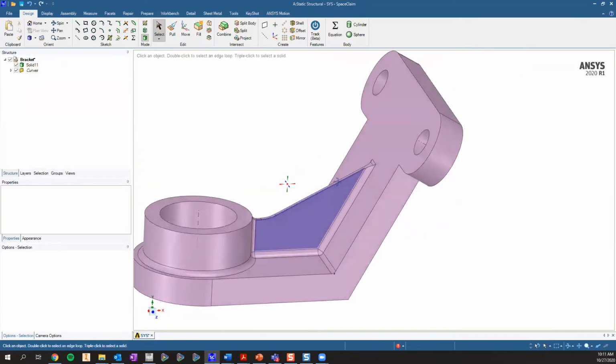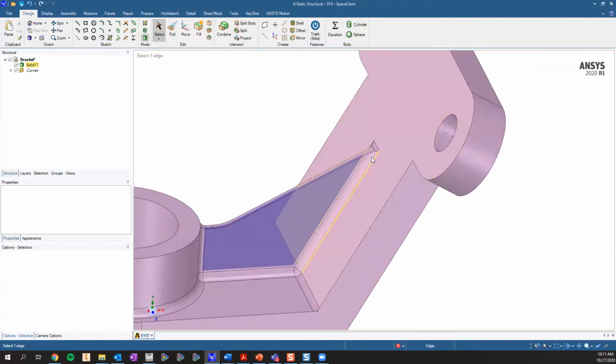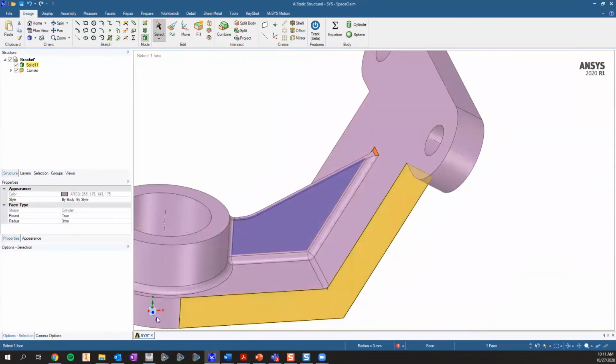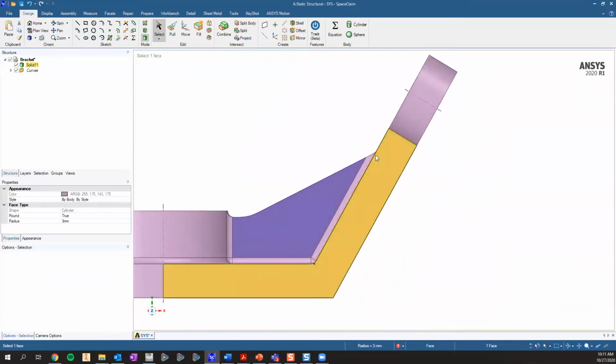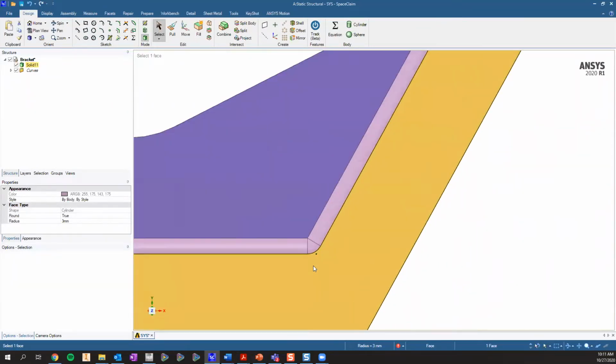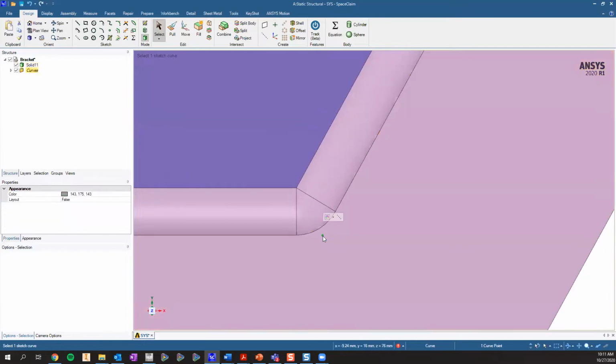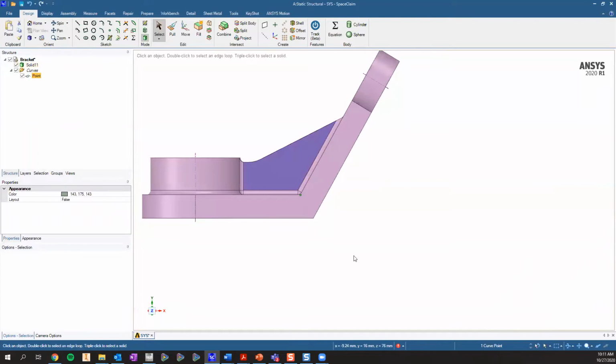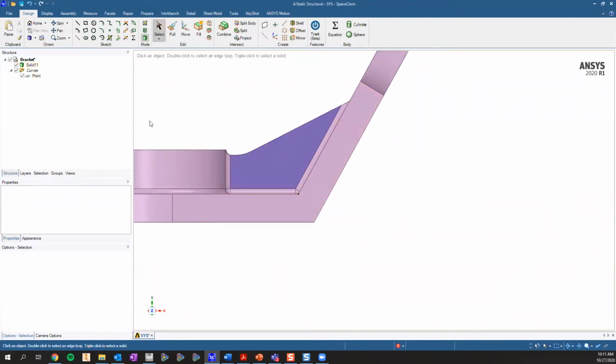And the next parameter set I'm going to make is going to be the height. So it's going to be this feature and its vertical dimension from this small point I made. I made this point from a sketch earlier. So you can set your parameters to a datum point. You can make your own datum points. And I'm using this point as a datum right now.